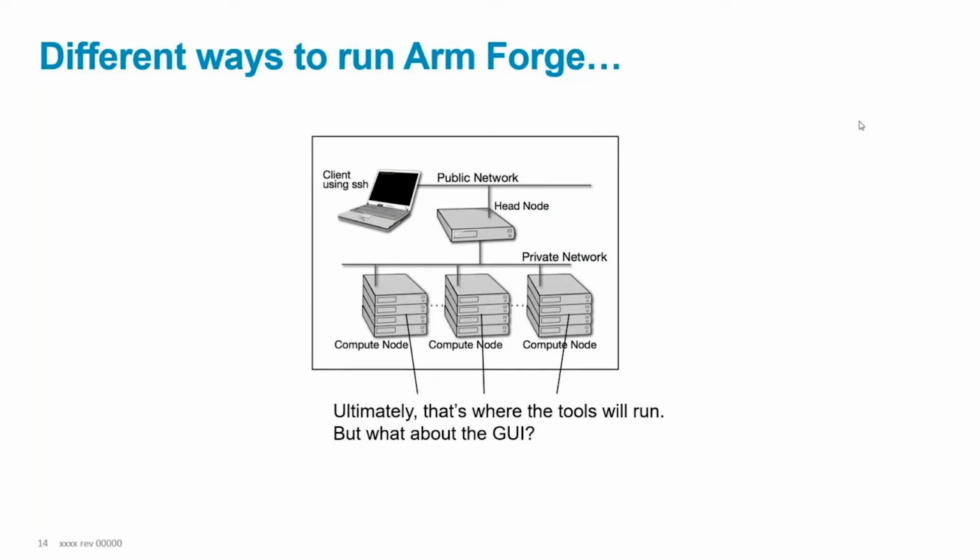For interactive mode, you can directly log in on your login node and launch the software. And X11 forwarding, if it is there, will provide you the GUI. Otherwise, you can also remote launch it on your local machine, your laptop or your mobile workstation.